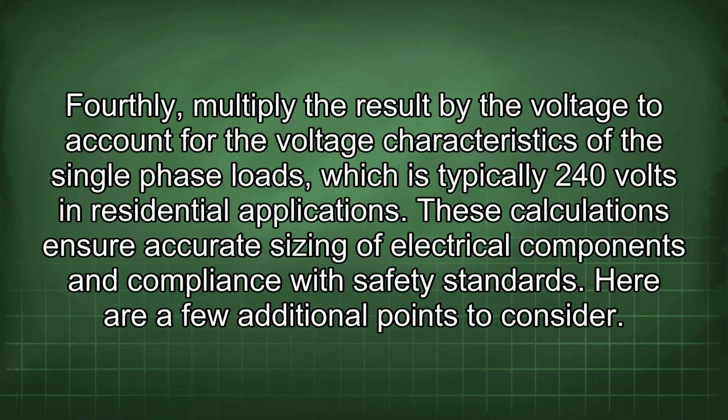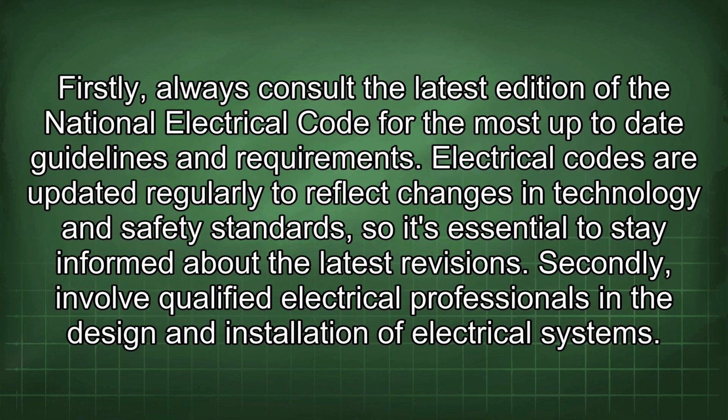Fourthly, multiply the result by the voltage to account for the voltage characteristics of the single-phase loads, which is typically 240 volts in residential applications. These calculations ensure accurate sizing of electrical components in compliance with safety standards. Here are a few additional points to consider. Firstly, always consult the latest edition of the National Electrical Code for the most up-to-date guidelines and requirements.